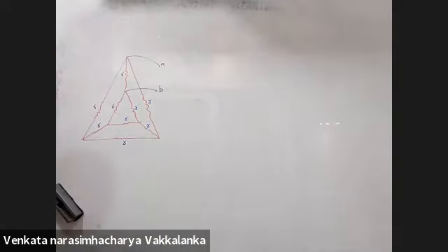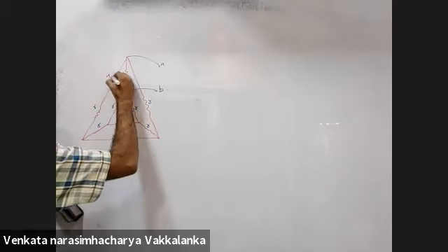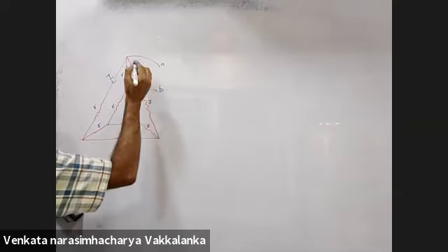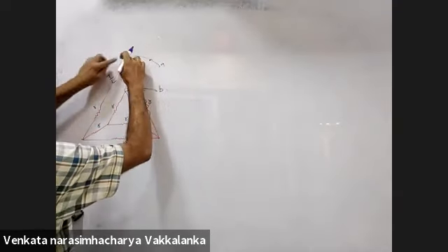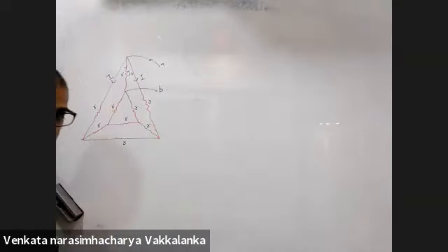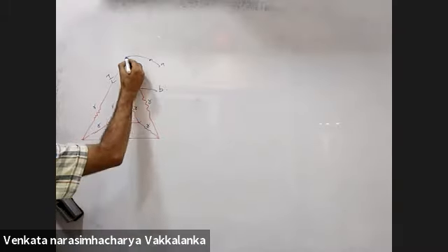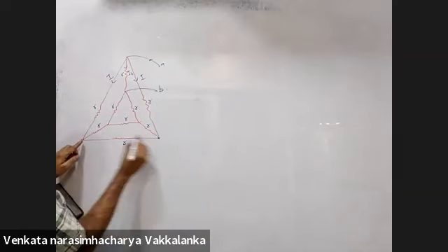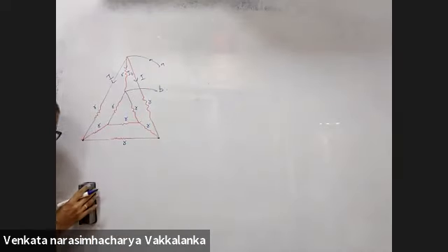Here the rule of symmetry used is: this branch and this branch are identical. Incoming current will split into these three branches. These both are identical branches. Do you agree with that? Yes. If these both are identical branches and equal current flows in, can I claim these both points are equipotential?